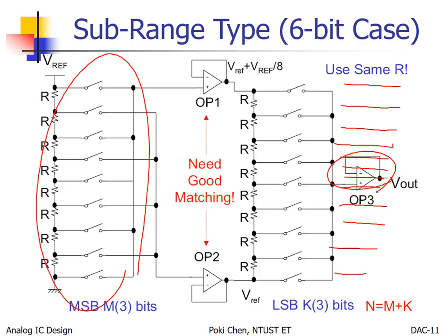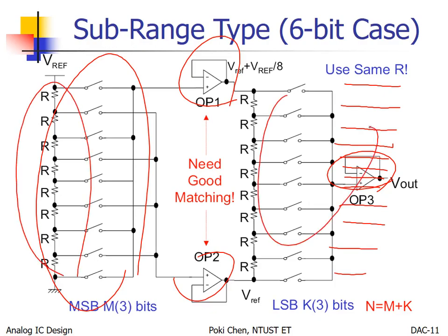If the difference between VOS1 and VOS2 is, again, much smaller than one LSB, you can make it. Okay? So right now, the pressure of design is put on op amp design instead of resistor layout. Got it? Okay. Bingo. That is what I can help.